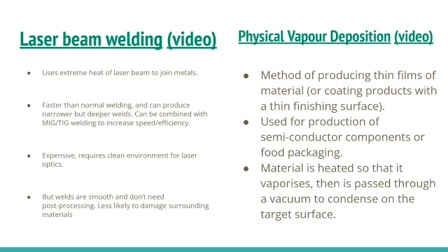like dust, the more it's exposed to things like fumes, like smoke, or burning deposit from the actual metal, which will then create essentially like tar on the surface of the glass, or imperfections or impurities will stick to the glass. So it needs regular cleaning. The laser cutters at school get cleaned quite regularly, and very often, if the laser cutter is not cutting through something, most of the time it's because the optics are a little bit dirty, so they need a clean.